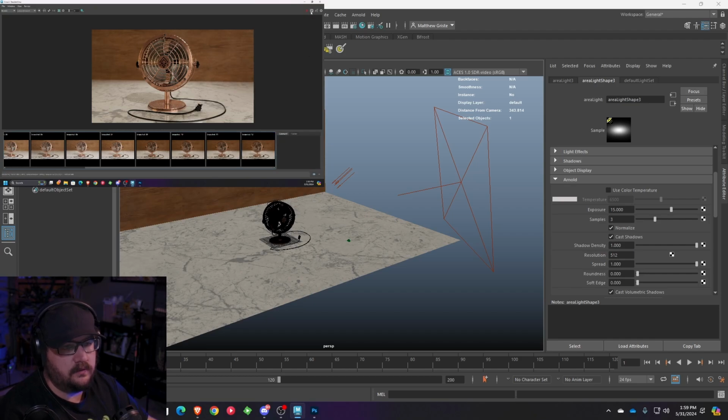All right, turn that off, render again. Okay, we're gonna see if this gives us a cleaner result. And you can see once again, it increased our render time. And this is just kind of the unfortunate result of rendering: as you go through your scene and increase your samples, you are going to increase the render time. So we went from 19 seconds probably to about what I'm going to guess is about 45 seconds.